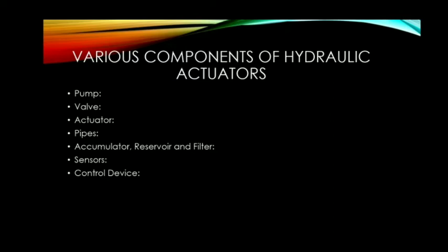Hydraulic actuators, as used in industrial process control, employ hydraulic pressure to drive an output member. The fluid used in a hydraulic actuator is highly incompressible so that pressure applied can be transmitted instantaneously to the member attached to it. A hydraulic actuator consists of a cylinder or fluid motor that uses hydraulic power to facilitate mechanical operation. The mechanical motion gives an output in terms of linear, rotary or oscillatory motion. Because liquids are nearly impossible to compress, a hydraulic actuator can exert considerable force.